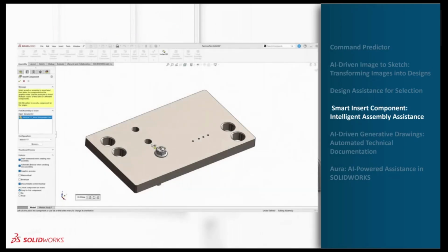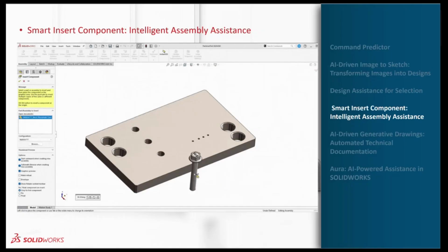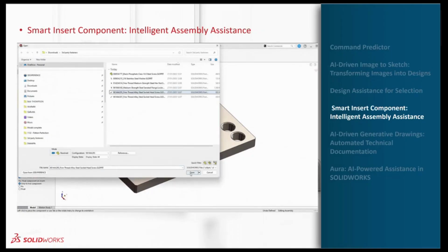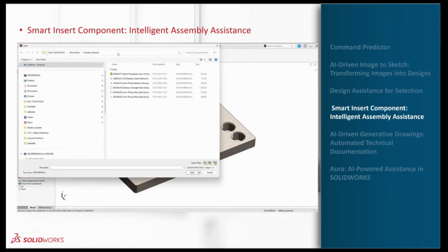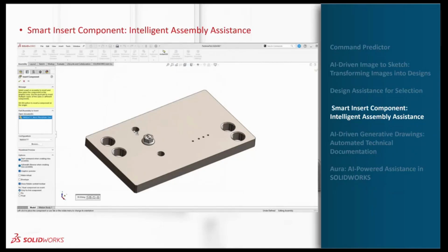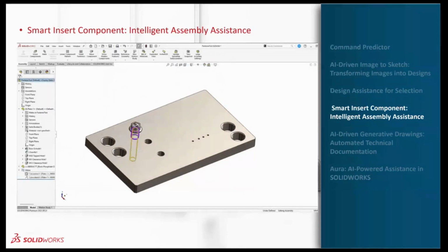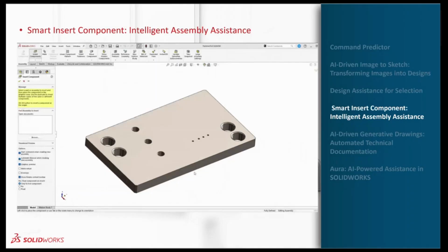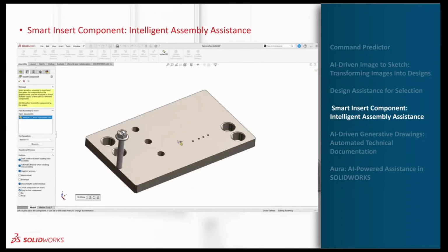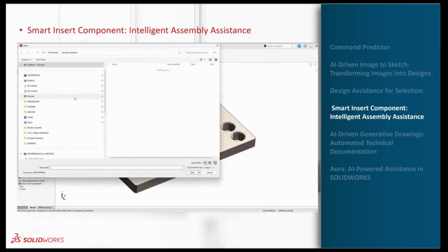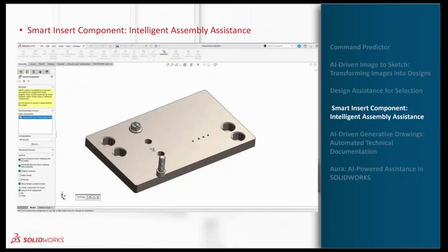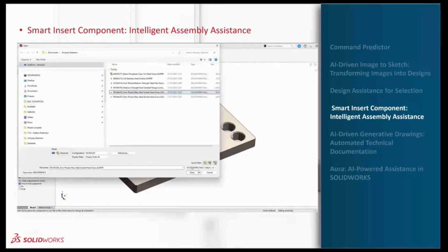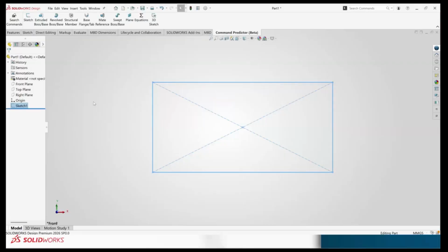it automatically detects the size, and it will automatically position. Even if you place it into other holes, it won't take. That kind of AI technology is what SolidWorks introduced in SolidWorks 2026. Here, if you can see, by just simply dragging and placing into a certain hole, it will detect and position. If you try to add to different holes, it won't take. Why? Because the size is mismatching. That is the kind of AI technology SolidWorks 2026 uses in insert components. As I told, this option is only applicable for the toolbox libraries. So let us see this enhancement and how it works in SolidWorks.